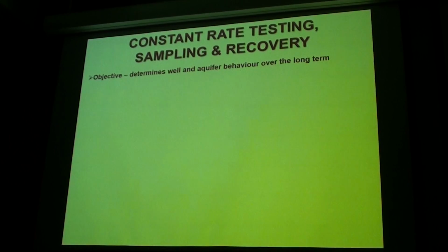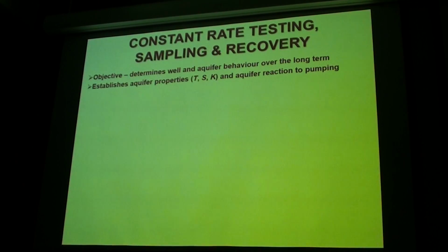Okay, we'll talk about those various methods of doing it. And you should do as many of those as you can. Okay, get as much information as you can from your pump test. You only get to do it once. It's expensive. Okay, it takes a long time to set up. It takes a lot of effort to monitor it and control it. And it's really important that you get good data. Make sure you get good data and then do something with it. The maximum you can with it. This will establish our properties.